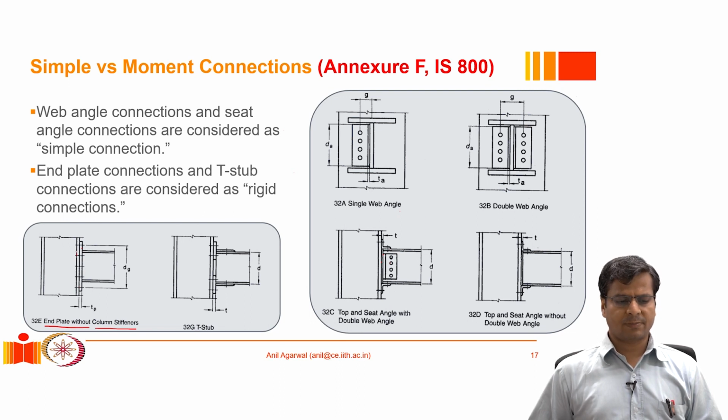And sometimes, in spite of this, you might realize that the flange itself or this local area of the column itself is not rigid enough, so that it can resist the force demand that is coming from the flange. So one way to address that issue is to increase the thickness of the end plate, and sometimes still that may not be enough, and we may have to provide stiffeners in the column. Both of them are acceptable approaches.